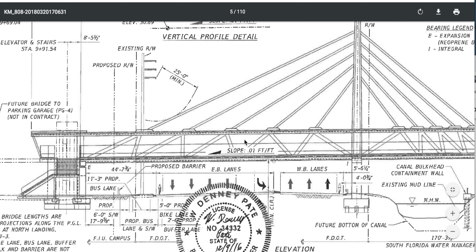So we come over here to this structure. This is the FIU bridge. We'll only use this structure here, please. This section here, which we know collapsed. Now the same thing applies. Naturally, the dead loads, the unsupported spans. That means here's a support here and a support here, the column here. This is the river, over where the failure was, down here. As the unsupported span, just by default, everything will want to deflect down in the center.